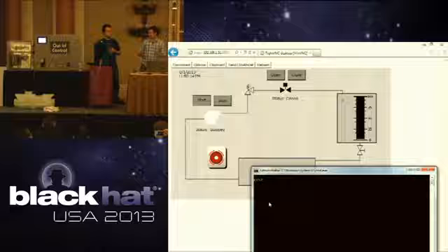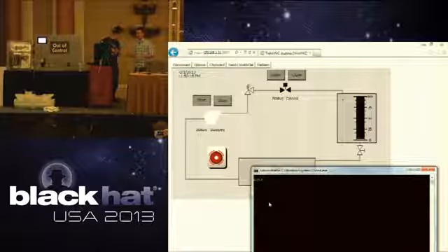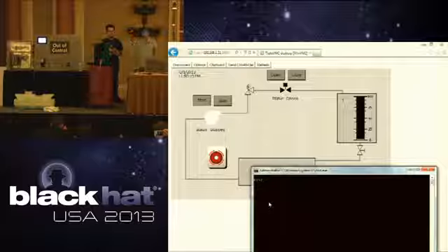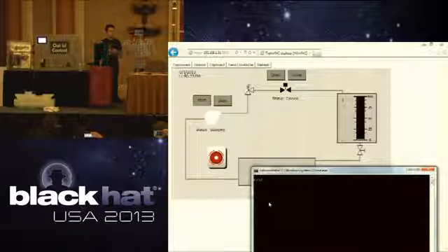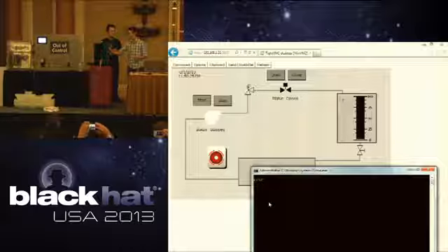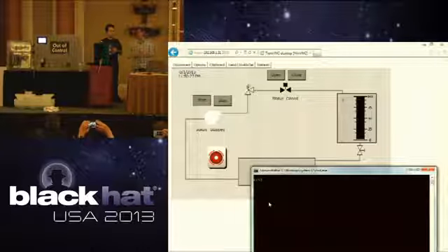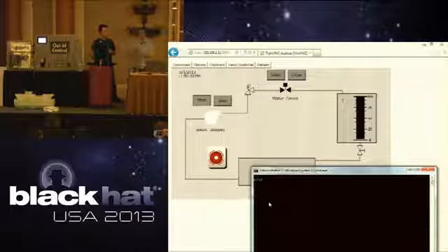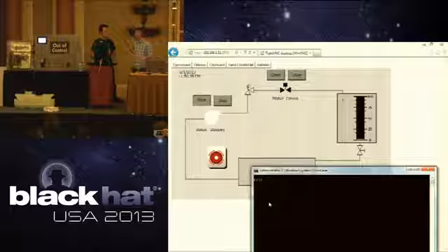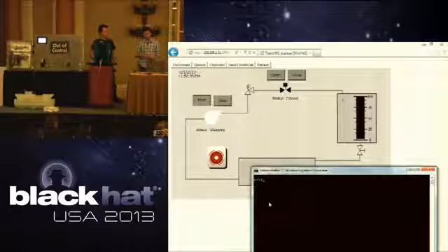Right. So this just kind of shows how easy it can be to force the outputs of a process. And this is not binary exploitation. This is just telling the PLC what points to turn on and off and what its worldview of the process is, and telling it to disable its own logic scanning. All it does is what it's told to do. And the operator always makes control decisions based on what the PLC is giving it.